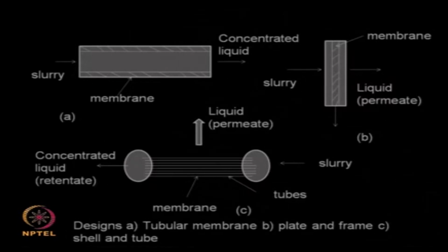So if you want to replace a tube, you need to open up this heat exchanger pipe, take one of these tubes which might have been fouled beyond use or might have been physically, mechanically damaged, then you can put another tube here and carry out your job. So that is another way of looking at this type of shell and tube design actually.